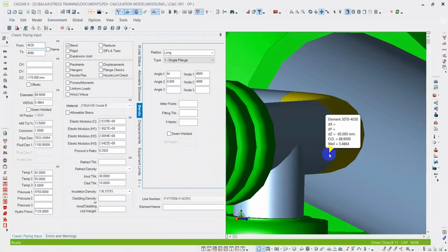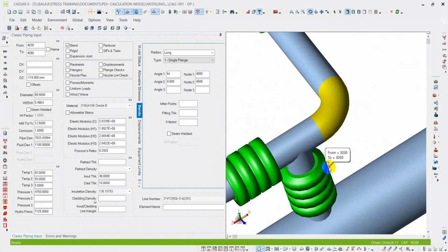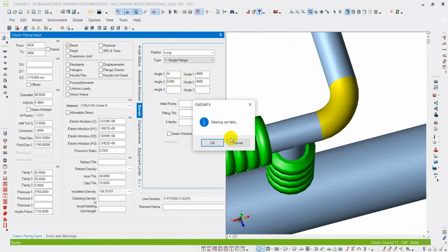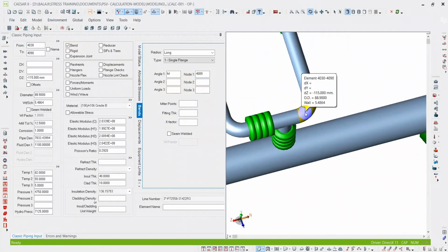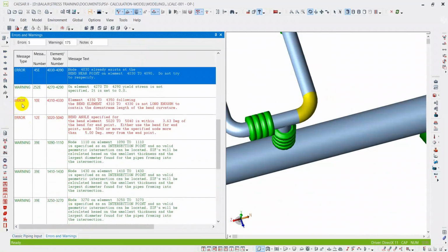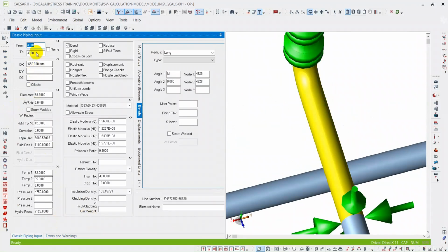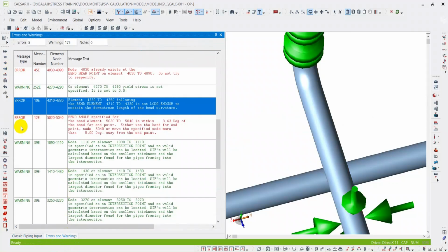4030. Yeah, this one I told previously. If you are given exact flange, elbow dimensions, then you have to double click this, or you have to delete this. You should have only the midpoint, because for all elbows, minimum 3 nodes should be there. Go to the next node. You select this one, on the error you go. Again the same error only. If you go to vertical, you have to change it to 114.3.